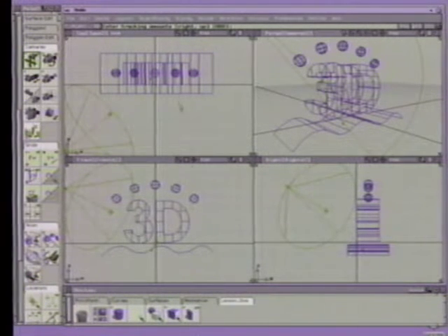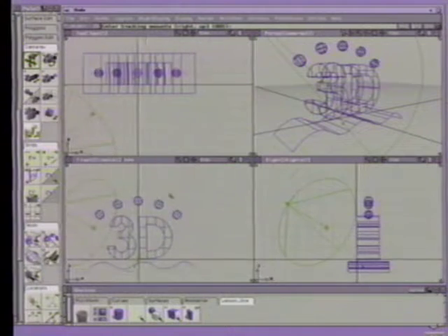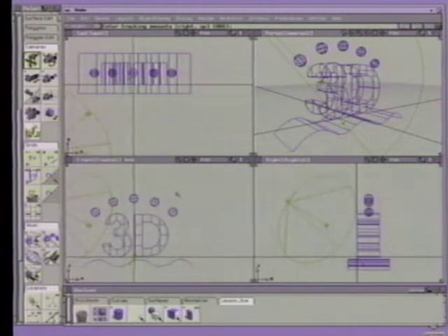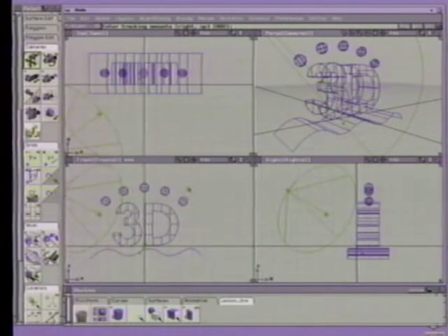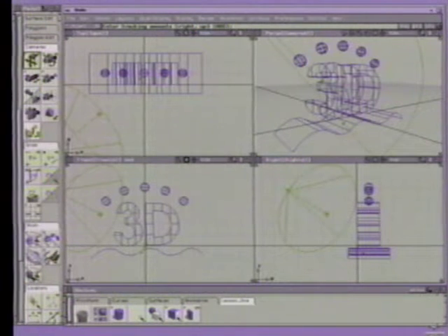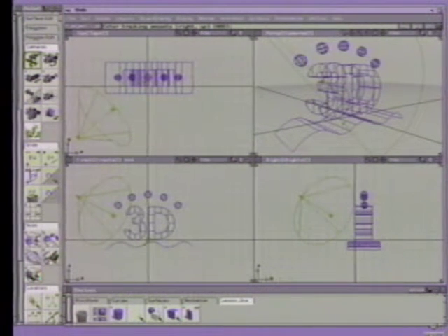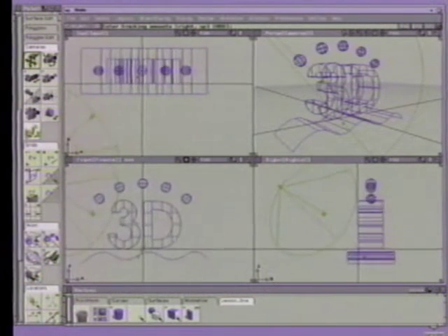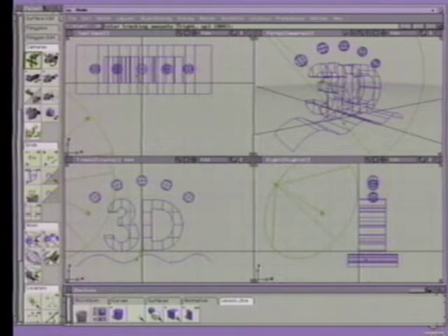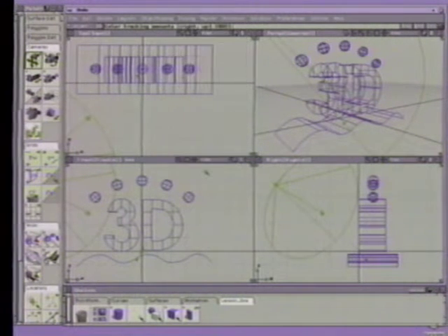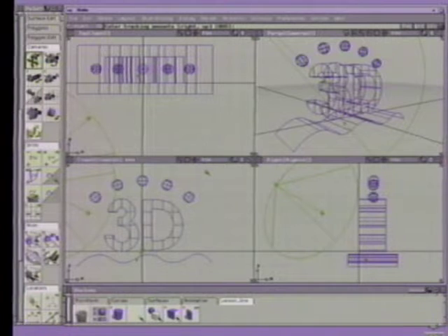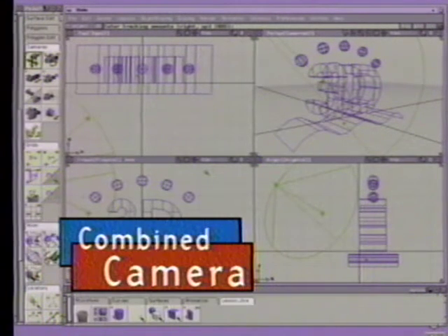With the Track tool, click-drag in the front window. Watch how the left-right motion is picked up by the top window and how the up-down motion is picked up in the right window. Now dolly into the window to get closer to the objects. Once you are happy with the results, turn the toggle mode off. This toggle mode is very useful when you want to ensure that the orthographic views match up at all times.